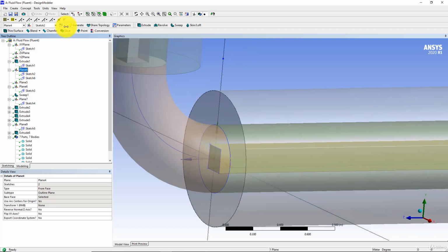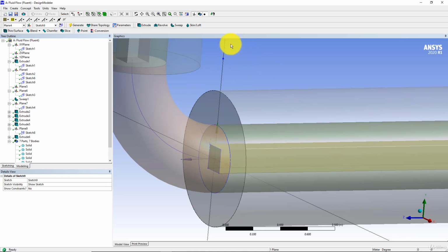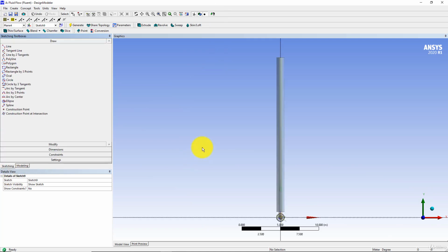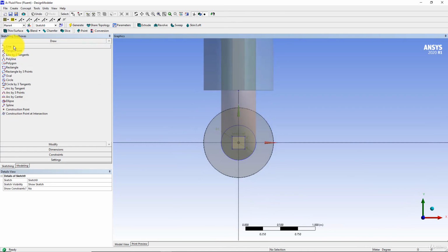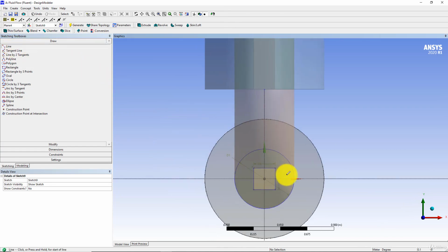And so again we have to create a new sketch here. Click on look at, and sketch 9 should be selected here, and click on look at and go back to sketching mode. From sketching mode we are going to create simple lines, and the lines start from this square corner, and the P symbol should be displayed, and then put the lines anywhere on the screen like this